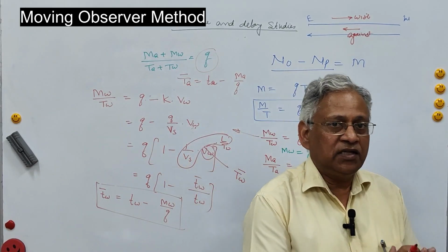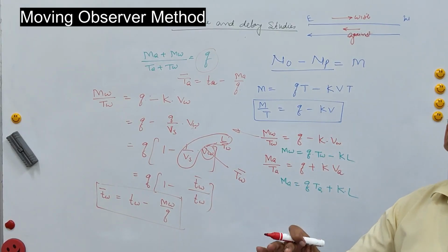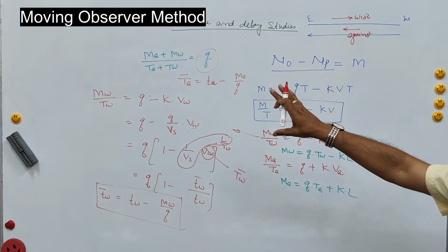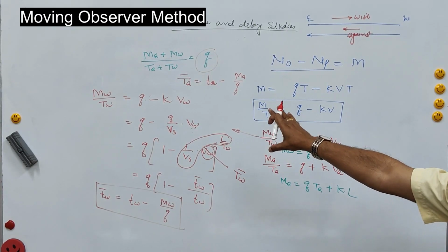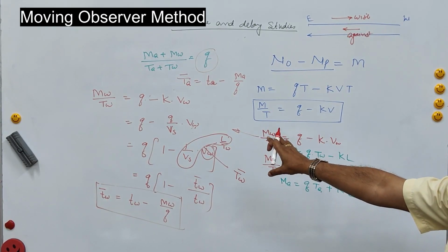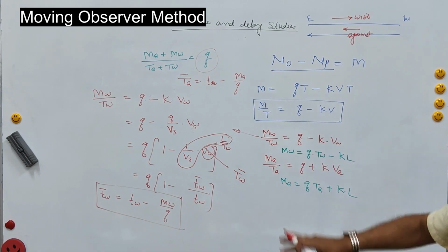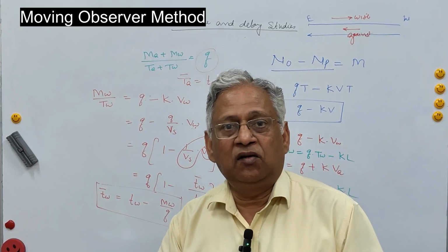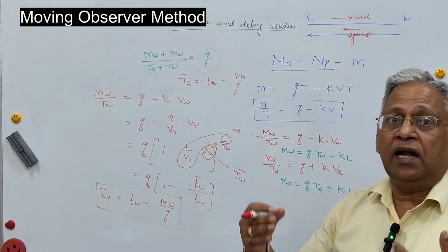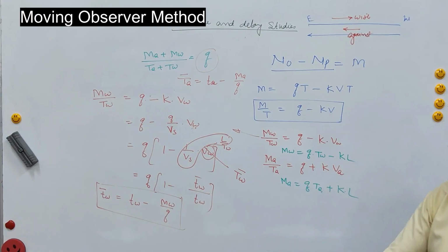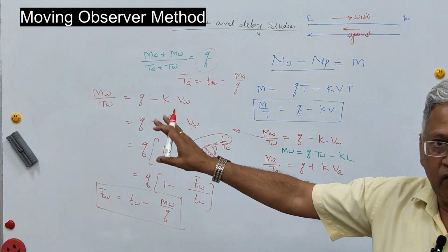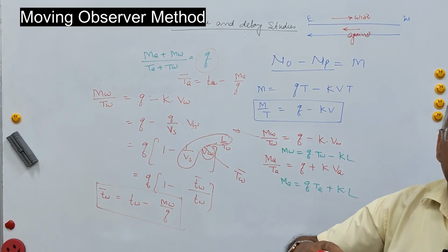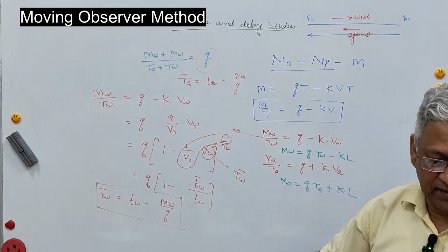Now, once you know the average time and the length of the section, you can find out the stream speed, that is, the speed of the stream. So you can find out all three parameters of traffic flow, Q, K, V. Now, this is very important to know the travel time or quality of flow on a corridor, and you can plan the improvement. And after improvement, you can again do this survey to find out how much travel time has increased or reduced by implementation of a traffic management measure.